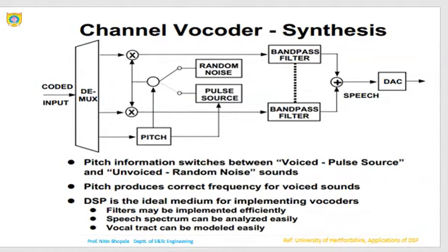To its original frequency range. From the block diagram of vocoders, it is quite apparent that most of the blocks can be implemented with contemporary DSPs. Filters are particularly easy to implement and their processing is well within the range required by speech signals.